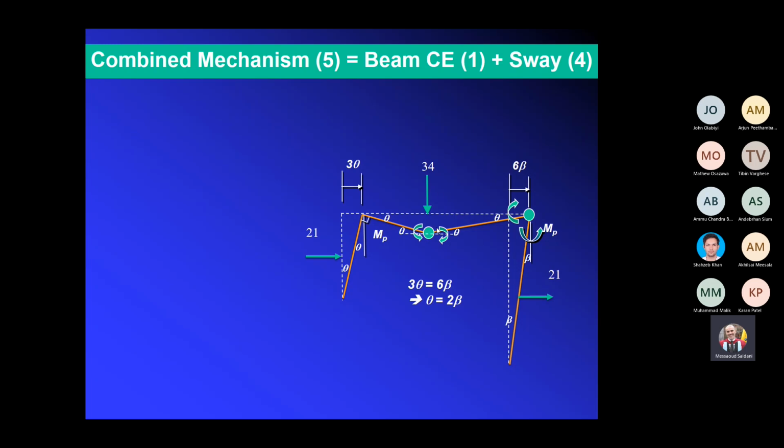And we only have a hinge at D and the hinge at E. All right. So what you can see here is that now we have only 2 hinges, which is exactly what we need for total collapse. So this is a total collapse mechanism situation, right? And we have the vertical load and we have the horizontal loads as shown.